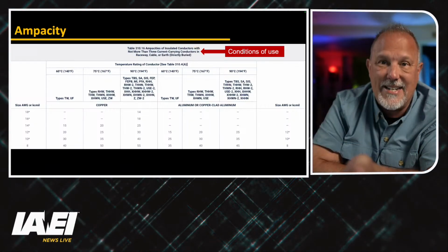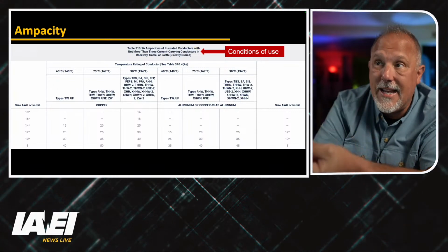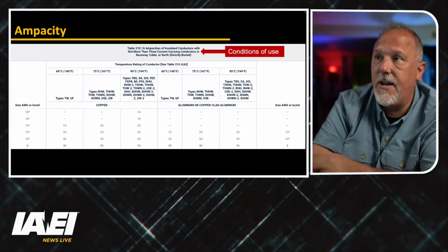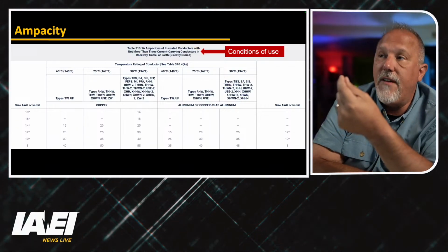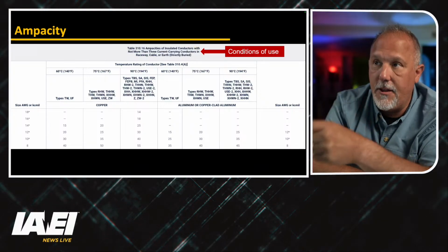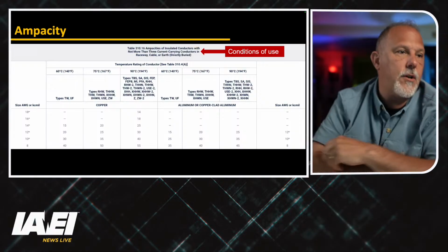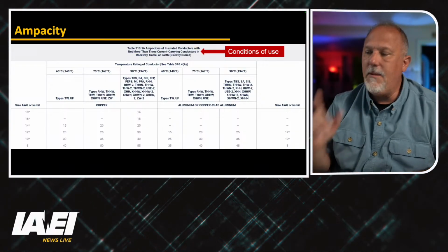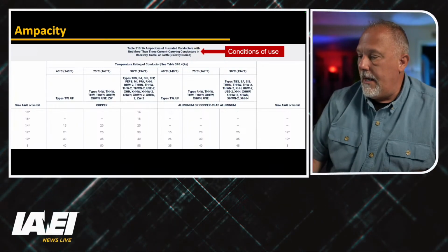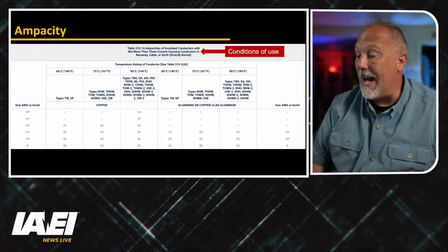We have an ampacity of a conductor, which is based upon conditions of use. In this case, we know that the table includes the ampacity values when you have an insulated conductor with not more than 3 current carrying conductors in a raceway, cable, or direct buried. And if you go to the note, I didn't put the note in here. Let me pull it up on my iPad.